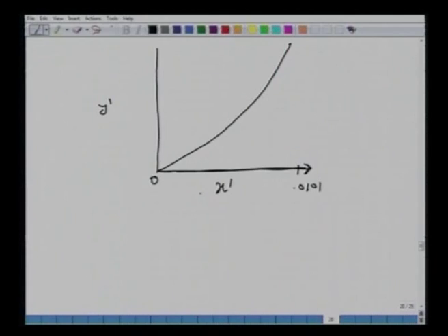So go back to the equations, the first operating line equation. We have the slope of minus A over B. Here of course is one stage. So the slope of this operating line is minus 99, that's water, divided by 150, which is minus 0.66. So this is XF or XF prime dash.